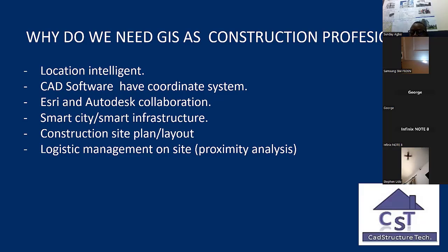And then when AutoCAD says you should specify first point, what you need to do is put the coordinate of that place. And then you follow the direction or the orientation of that particular design, so that if you finish that drawing, and then somebody else, maybe a land surveyor or a town planner, overlays it with their own layout, it will actually fall at the right position.